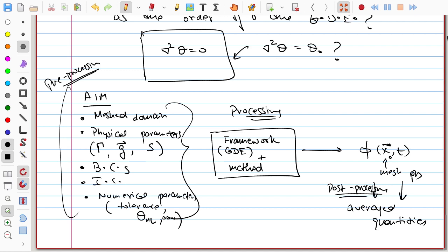So the problem we have here is that you have a pipe which suddenly expands. It has a name called backward facing step, but it is simply a suddenly expanding pipe. There is no gravity here, but what happens is that when there is a flow happening and then suddenly an expansion happens, you see that there is a region where the flow starts to circulate. So the fresh flow will only go from here to here. This region will simply keep circulating. Okay. I mean, why are we solving this? Because sudden expansion can have a significant effect on the flow situations in pipes, but for now let's take it as a numerical challenge to solve.